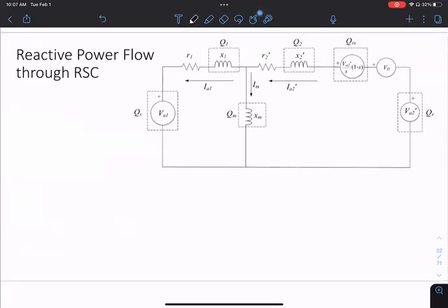So I have SR, right? Now what I'm going to do is look at the complex power, the total complex power coming out of this. So the complex power SR, this is 3 VA2 prime, IA2 prime. Remember to conjugate the current, right? So this will tell me the active and reactive power flowing out of this, plus jQR, right?